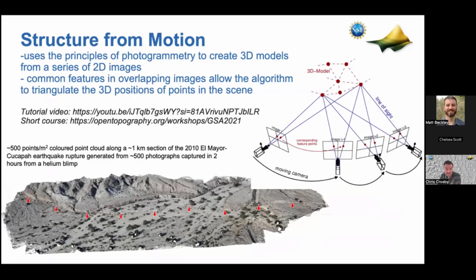And the way this works is unlike traditional photogrammetry, where you need to understand the position of the aircraft and the camera parameters for the images that are collected. So those of you that use a stereoscope and mapped in 3 dimensions on aerial photography, maybe you did this years ago in a class or something in school, structure from motion doesn't really require the same constraints in terms of the collection geometry or the camera itself.